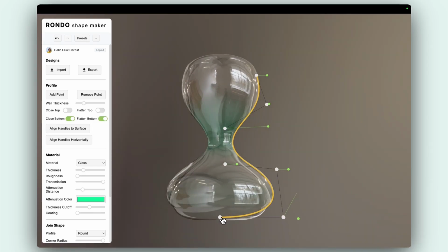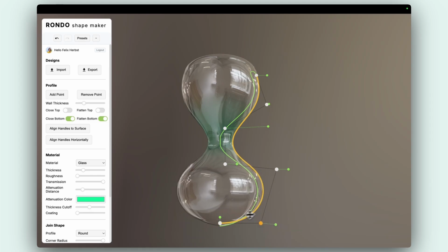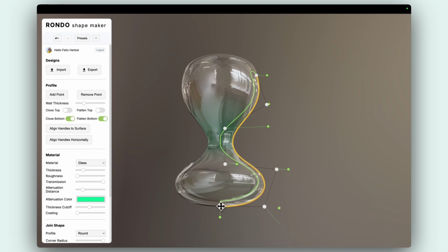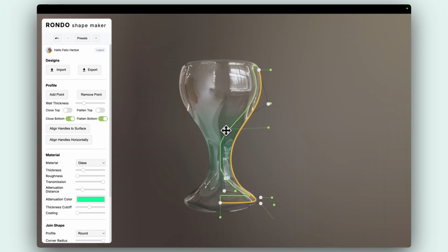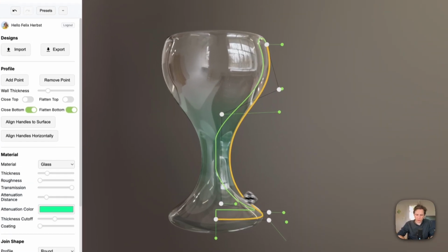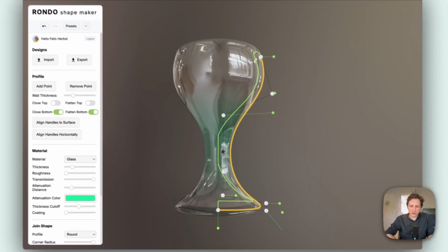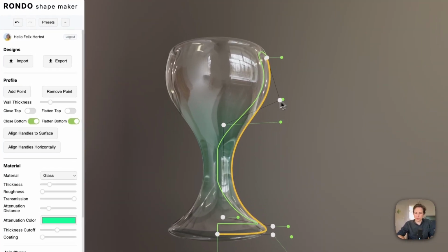And what this does is it adds some constraints to these control points here, so that you can't move them off this plane anymore. So it's now constrained to be a flat surface. You can see that even when we move these splines into a wine glass shape, it's still not thin enough in the middle. And that's because we don't have enough control points here.